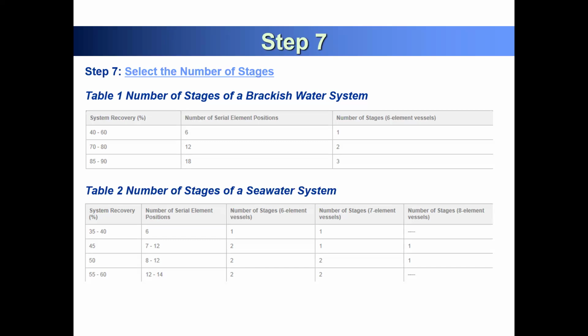So you have 10 pressure vessels. With 3 stages, which one is the best way? 5, 4, 1 would be 10 pressure vessels you can allocate. First stage 5, second stage 4, last third stage 1. So you have 10 pressure vessels.